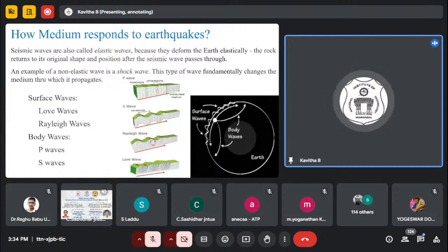That's the basic difference. Why do I want to study the medium or the type of earthquake waves? Because this tells you the different types of movements your structure is going to experience when an earthquake comes. For example, you may design your structures only for horizontal movement. You may imagine that because of the event, I'm going to get only horizontal movement, so I will design my structures to safeguard only against horizontal movement. But that is not true.